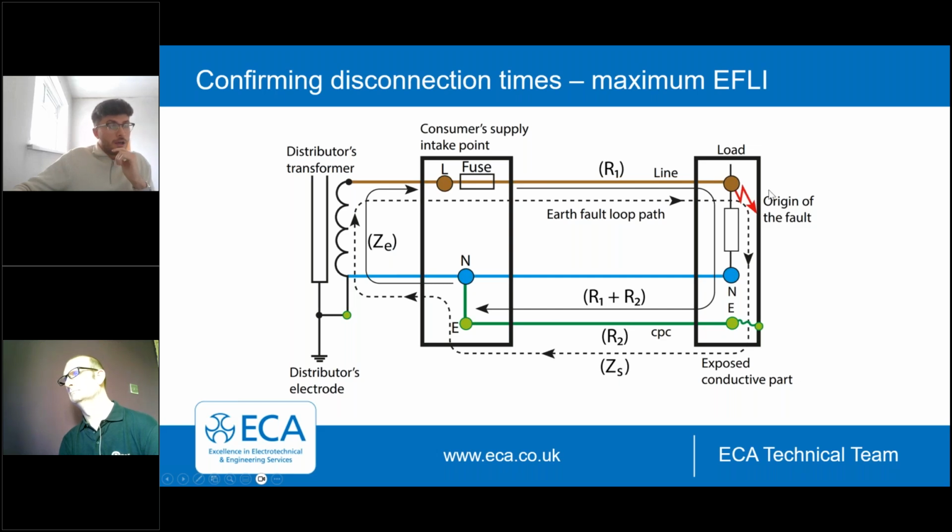Now this fault current will then travel back through the circuit protective conductor, back through the earthing conductor, and in this case back through the PEN conductor, with this being a TN-C-S earthing system. It will go back through the distributor's transformer, back through the supply line conductor to complete a loop, and then it should hopefully disconnect the protective device nearest the origin of the fault. So that hopefully describes what happens in the event of an earth fault, and in order for it to be suitable, we need the impedance to be of a suitably low value, which should then give us a sufficient fault current.